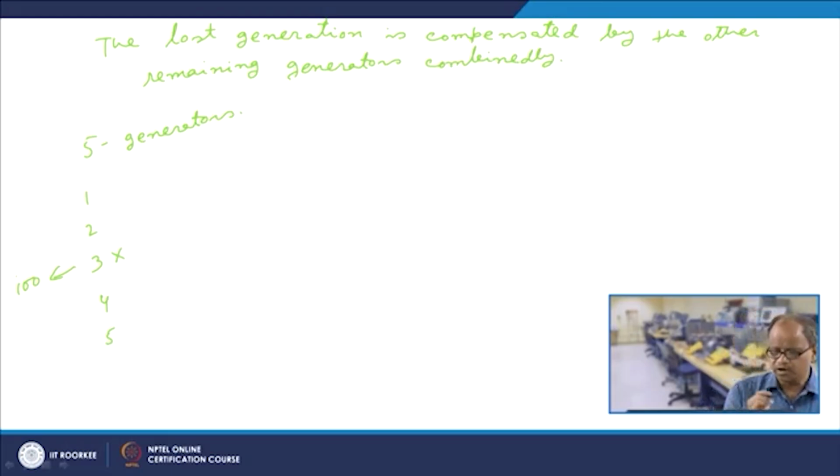So, we define some quantity called gamma L, where actually we distribute them according to the amount of real power which they have been generating, or rather we also sometimes do it through their MVA.